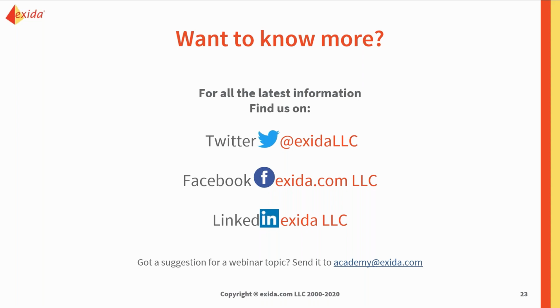First of all, your safe failure rate should always be on the certificate. And if it's not on the certificate, I would start asking, well, why not? Was this not evaluated for a low demand rate where there could be some safe failures? Was that not in the context of their evaluation?